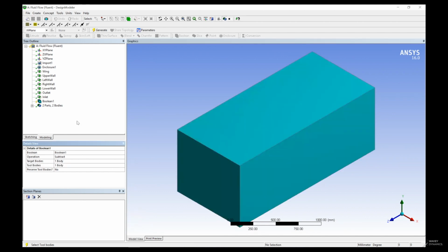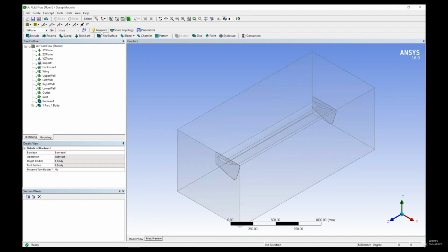Then when we've done all that, an important consideration is that, in a similar way as I was saying, having a domain too large is computationally intensive, you can assume that a solution that will get you a good approximation is to treat the airfoil in a symmetrical manner. So you can assume everything around the center line, everything to the left and right, would be a mirror of each other. You can actually do that at this point by cutting the domain in half with a special tool called symmetry. So I'll do that.